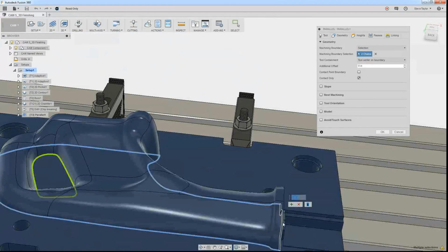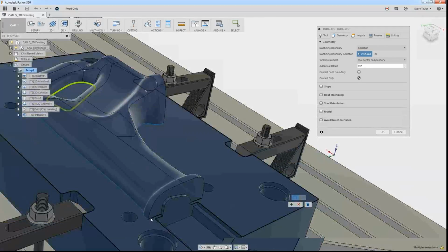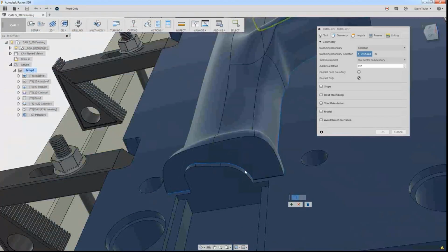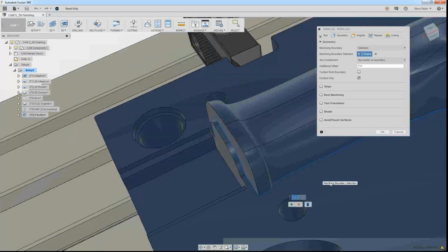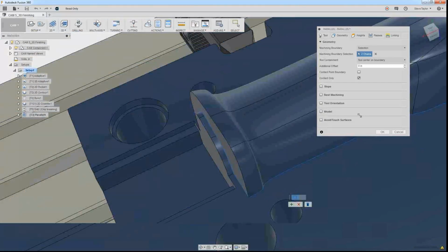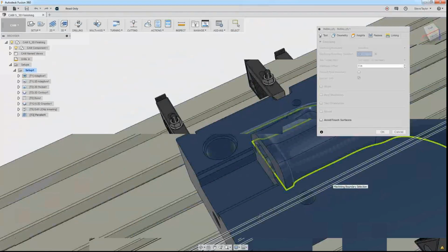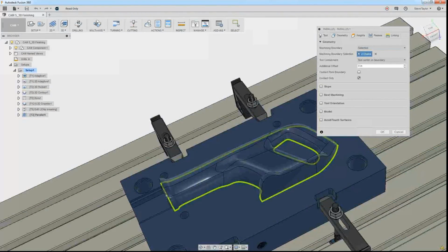Got it. And then we need to come into this bit here. I need to select that, there, and there. So we've actually now got all of the sections around it. There. So if I click plus, that will add now the outer boundary. So we've got the inside of the handle and we've got the outside. We want to make sure the contour is closed, but it could be open or closed, but on this one we're going to make sure that it's closed.